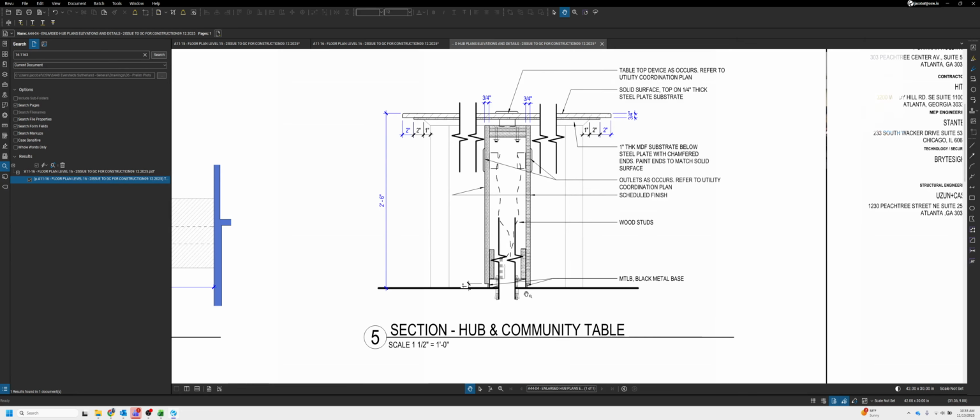So we know that there's a die wall in the middle of the table. Looks like there's going to be some kind of an outlet built into the top and outlets built into the sides of that die wall as well. So anytime you see a die wall with outlets, well, pretty much a die wall at any rate, but specifically anything with outlets or any holes cut into it or anything like that, you probably want to make sure that one side of your die wall is removable.